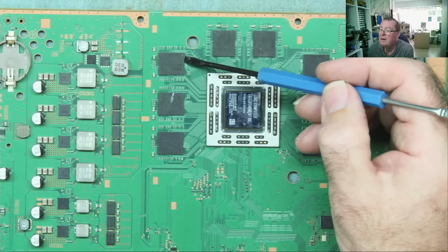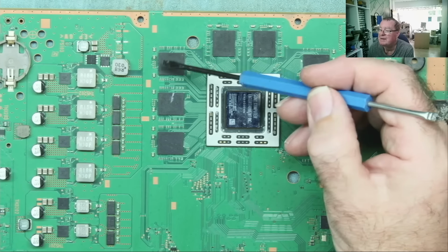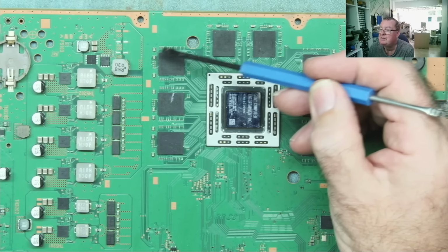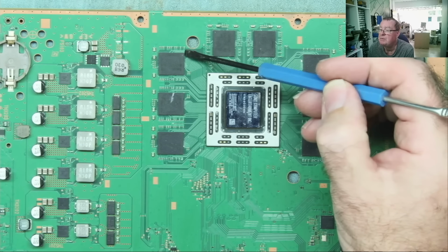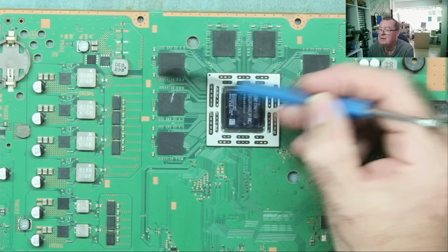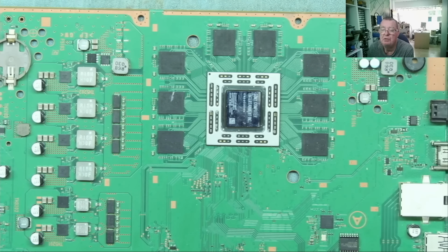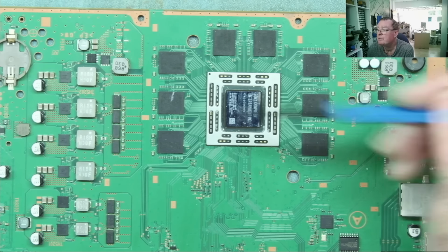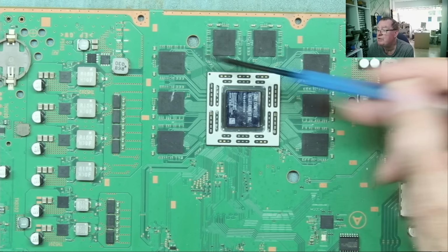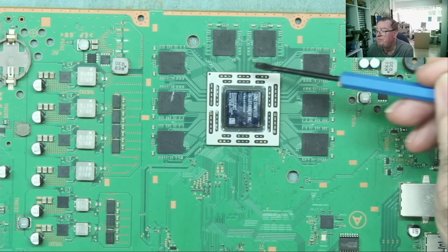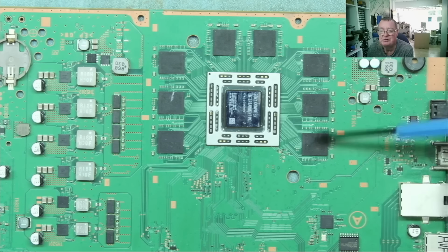Okay, and you'll find it just moves slightly then springs back into position. The reason it's springing back into position is the surface tension of the solder, but by doing that little bit of tapping you'll move it a bit and that'll cause the balls to resolder. If you have a fractured joint, that may well fix it. It's easier on smaller chips, it's harder on these bigger ones, plus you need better equipment to get this up to temperature to do it. Okay, but that is reflowing.